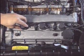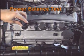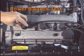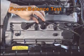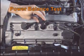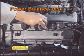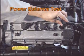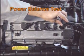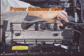For reference, when engine idle condition is not good, remove the high-tension cable from each cylinder one by one and perform power balance test, which compares the engine condition. Through this test, we can find the trouble cylinder, and we can solve the problem by inspecting the fuel system, ignition system, combustion chamber pressure, which may influence on the combustion in the corresponding cylinder.